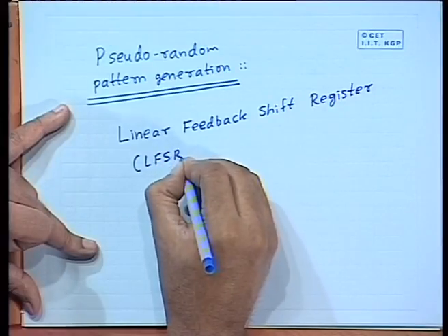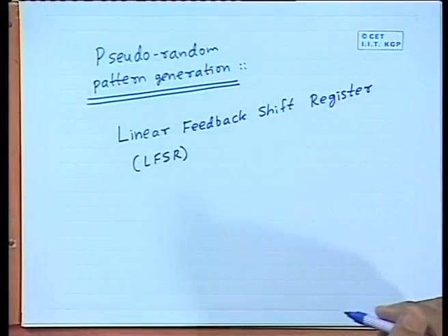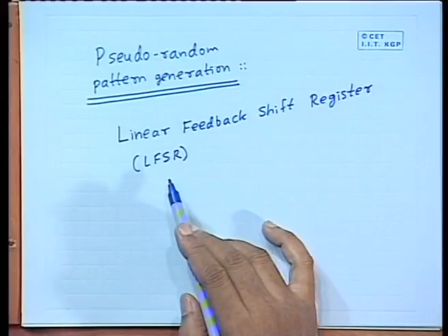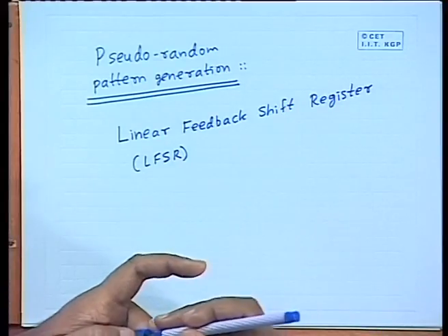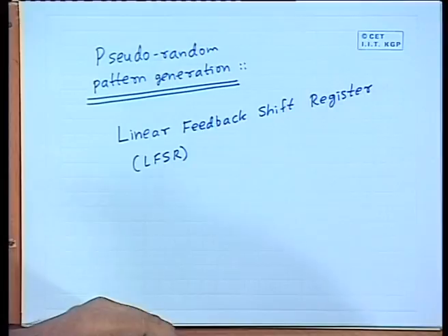We will see later how an LFSR looks like and what are its properties, but actually you can use an LFSR simply to generate the pseudo-random patterns and to detect the first few faults, in fact first many faults. So, the faults which remain to be detected will be detected later by using test generator algorithms. Okay.